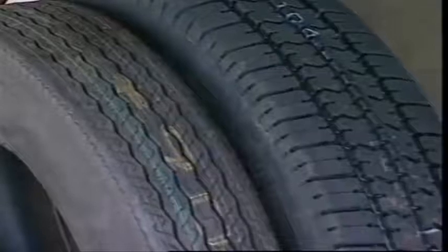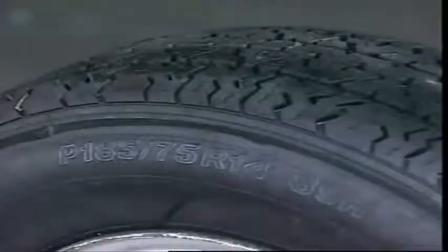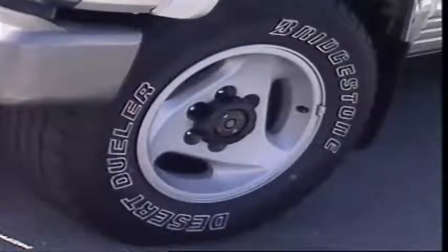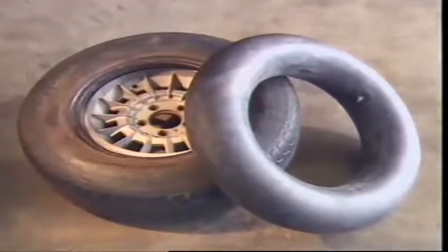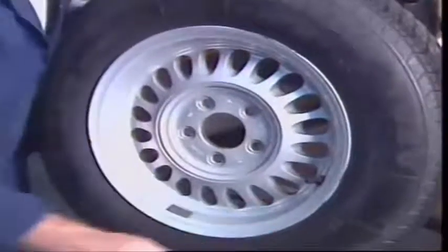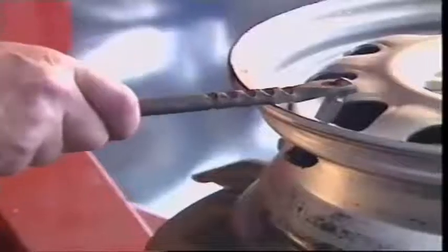Two types of tyre construction are common: cross-ply and radial. Most passenger cars now use radial tyres, and radials are replacing cross-ply tyres on four-wheel drives and heavy vehicles. Tube tyres require an inner tube to seal the air inside the tyre. Tubeless tyres eliminate the inner tube by making the complete wheel and tyre assembly airtight. A special airtight valve assembly is needed. This can be a tight fit into the rim, or it can be held with a nut and sealing washers.